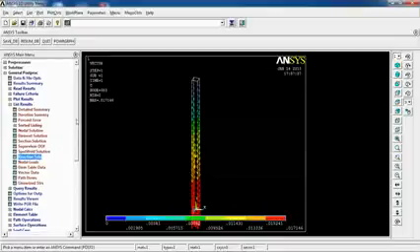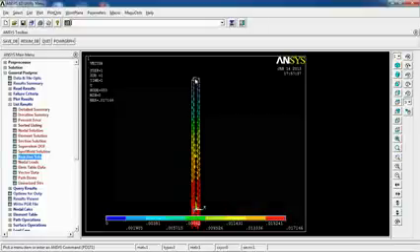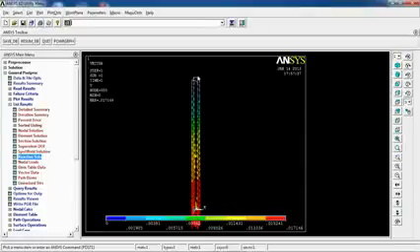So what you see in here is, probably, this is more accurate in analyzing a beam and its deflection based on its own weight, or even external loads, compared to yesterday's or lesson 7's example, which was completely engineering analysis without taking into account the change in cross-section area of the material as it expands because of its own weight.